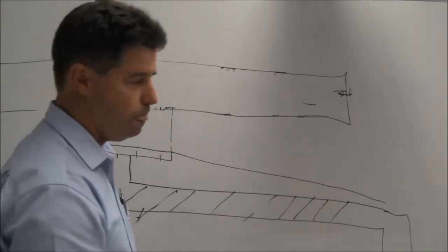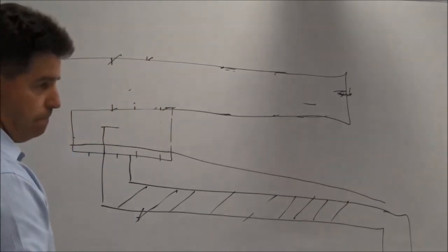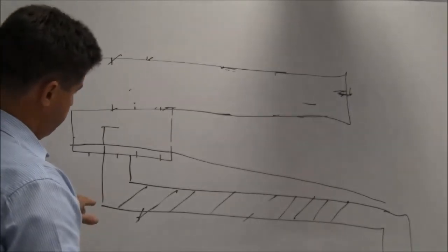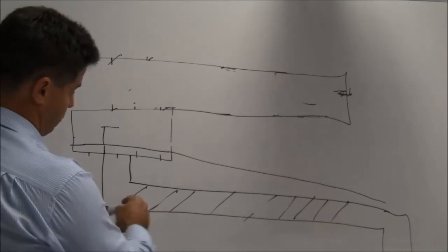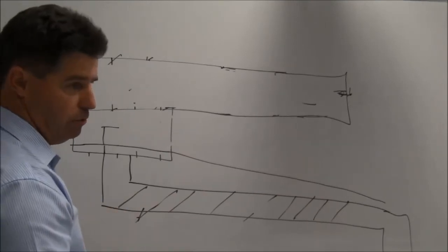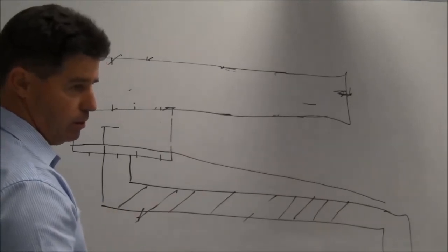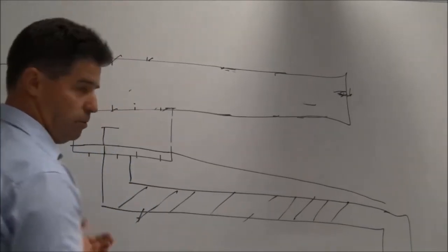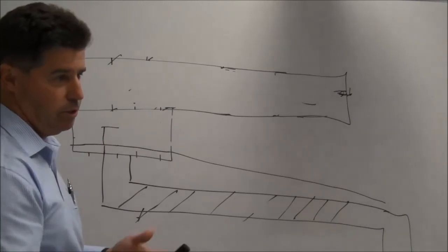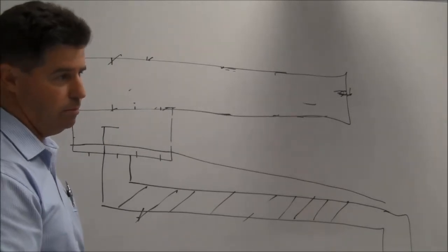So where does that come in? You said if the drop was greater, is that because the head would push the water down? No, the losses in the pipe itself. So if you're stuck for a height there, can you make your box gutter work? You can do lots of things. You can increase the pipe size itself. Yeah, just increasing the pipe size will reduce the losses in the system. Right.